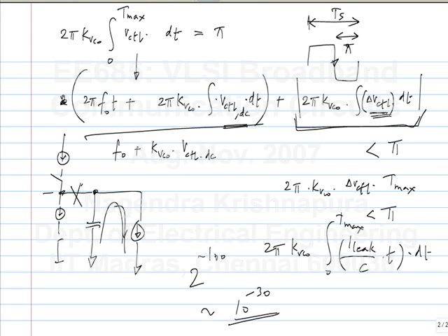But typically it's not so difficult to arrange it so that you can guarantee, let's say, one transition every 25 bits or 50 bits or something like that, okay? Now if you say that the data is purely random, then clearly there is a probability that you will have 100 or more than 100 consecutive identical digits. But the probability of that is small enough. Now if you are talking about bit error rates of 10 to the minus 15 and so on, this kind of probability of PLL drift you would ignore it. I mean, this is not the issue that is limiting the system, right? It's something else.